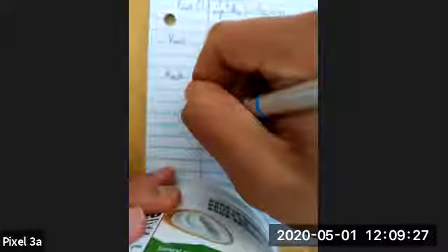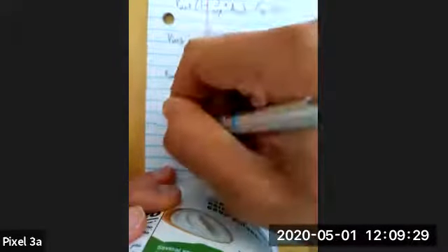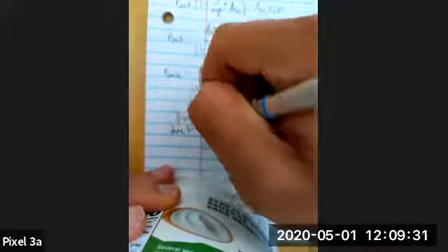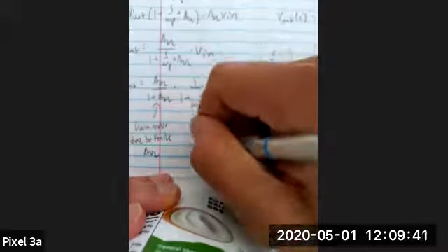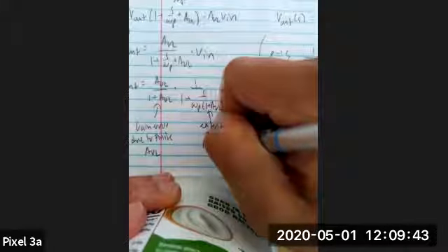And so in this form, we see that we have some gain error due to finite gain. And we also see an extended bandwidth due to loop gain. The loop gain here is just A open loop and feedback.